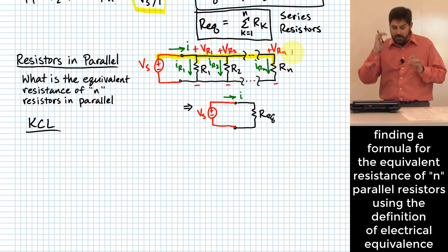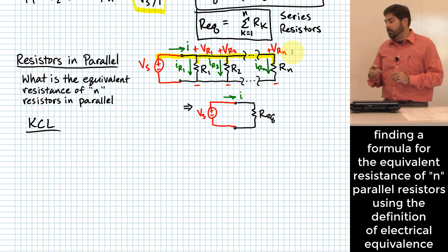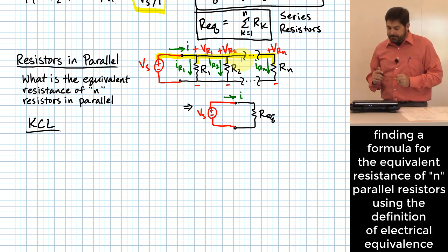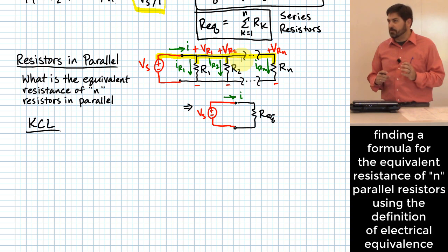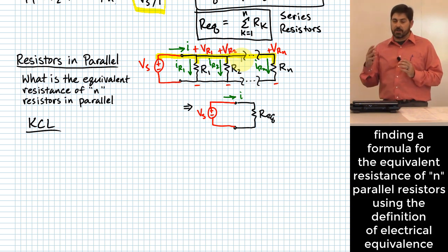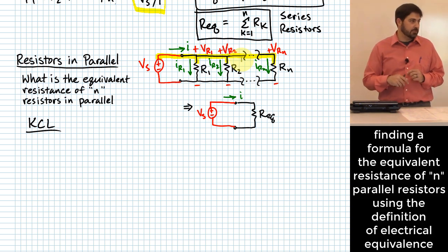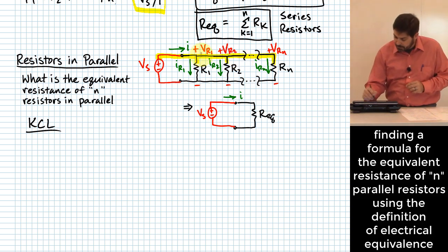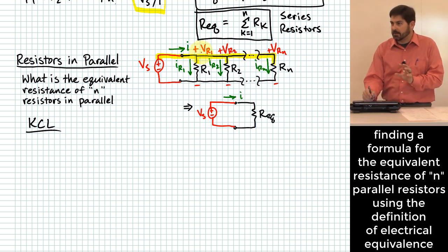So that's all one node up there. And anytime you apply Kirchhoff's current law, you do that at a node. So I'm going to do this for that node right up there. And let me identify positive values as actually being currents that leave the node. Okay? So what would I write if I wanted to do a Kirchhoff's current law equation for that upper node? Currents leaving are positive, that's how I'm going to write it, okay?